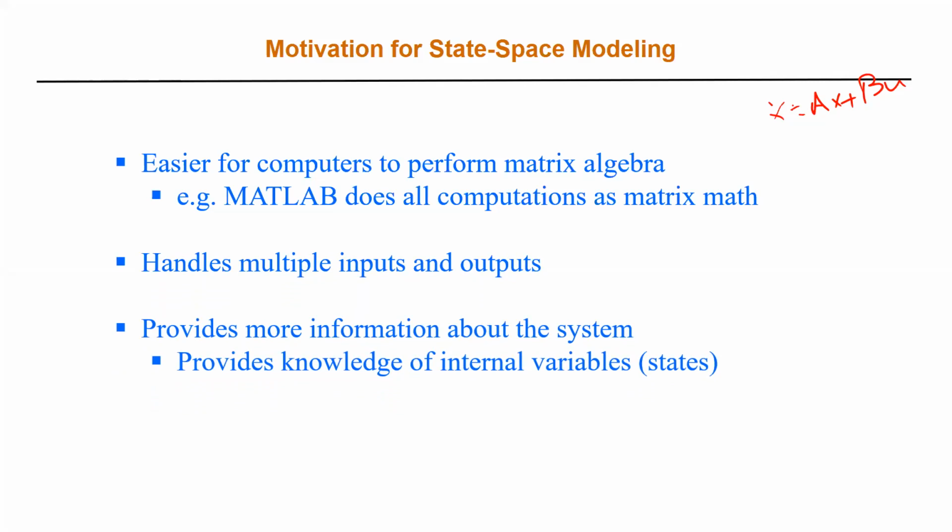Now, when you have a differential equation model and you want to get the transfer function, what do you do with the initial conditions? Set them to 0. But if the system has an initial condition and I get the output, you have to acknowledge them, and it will be hard to use only the transfer function. The transfer function model is defined for zero initial condition, so it will not handle any initial condition.